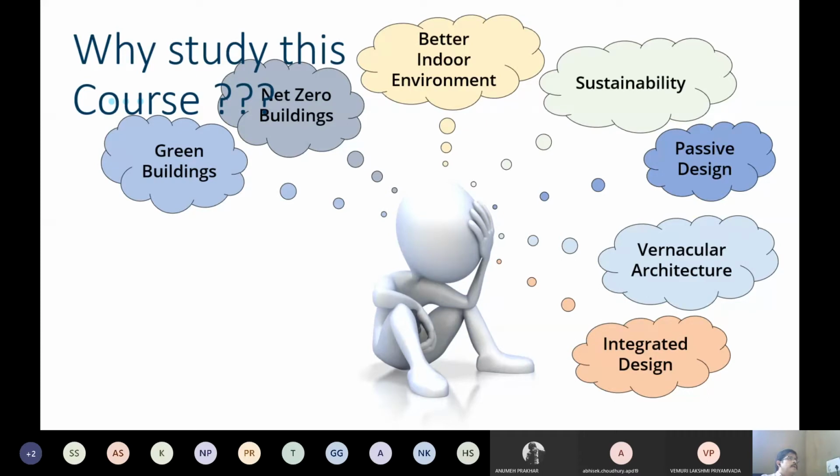When you're bringing it all the way across from Italy to India and to a certain location, say probably Dhanbad in Jharkhand, how much energy has been spent to bring it there and then place it in your project? That is the total energy which is embodied within that material. That is what is embodied energy. So manufacturing plus transporting, the energy entirely, by the time it has been used in the final place.